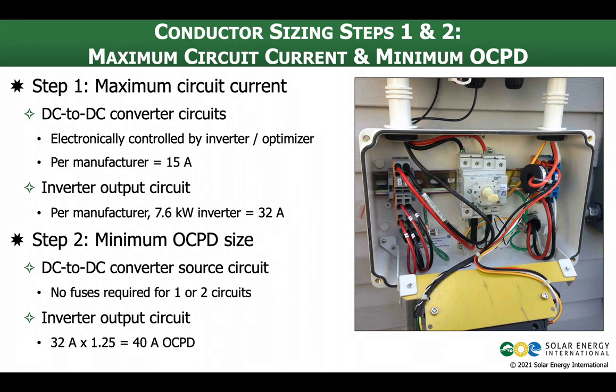One thing I did want to point out about this particular inverter, you can't exactly see it, but this little mounting bracket here tips down so that you can access the wiring. And on the front of that is a revenue grade meter, which is an option for this inverter. You can see a CT here for the output monitoring. And this is an optional revenue grade meter that can then be connected to the data acquisition system. In some cases, you may need that. In some cases, the monitoring may be done externally or by other means. All depends on what you're looking for.